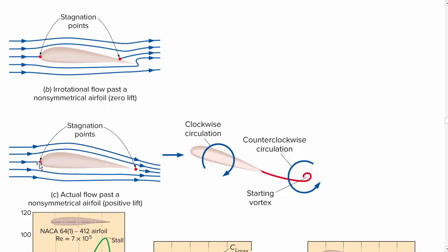So it's easy to look at this and say it's simple because it forces air to go faster around the top, and that means it increases speed and reduces the pressure, and that doesn't happen at the bottom, so you have higher pressure on the bottom and lower pressure on the top. That's true up to a point, but there's also complicated effects from vortices that show up near trailing edges and on wing tips.